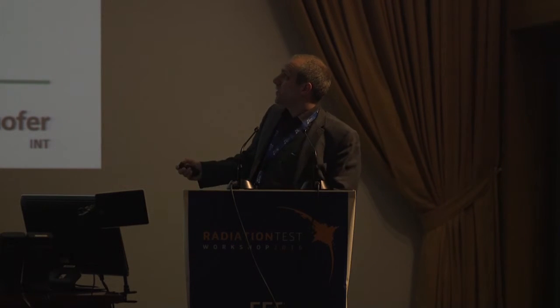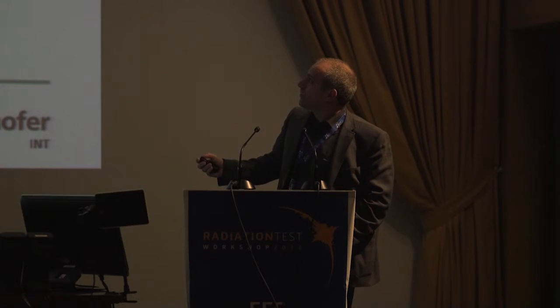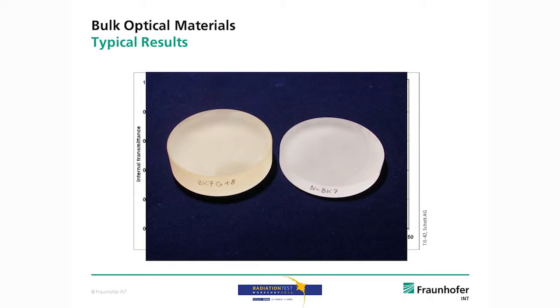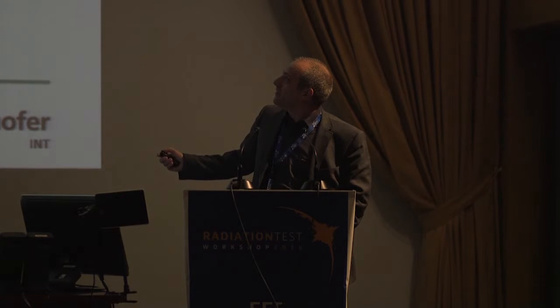As an example, this wasn't done with this setup, but this is from a manufacturer, and it's a very nice description of radiation-hard glasses. This is a non-radiation-hardened glass. Once you go away from pure silica, glasses get very sensitive to the induced losses. And here you see 100 gray, which is 10 kilorads for the electronics guys. And here you have 8 megagray, which is 800 megarads. And this is a hardened glass.